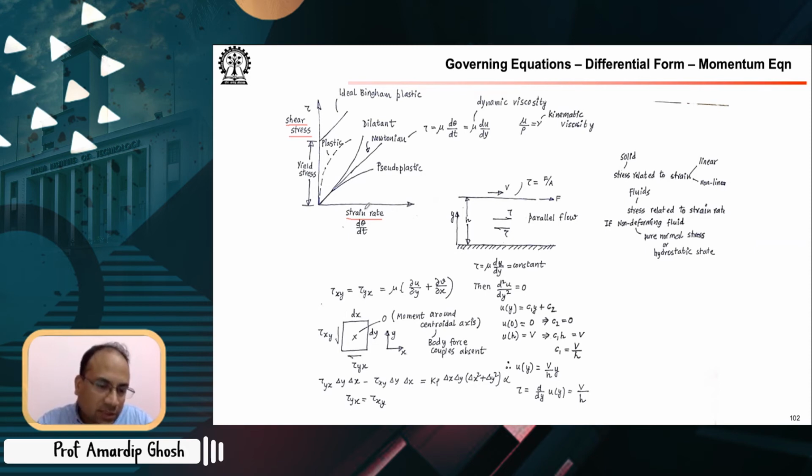So essentially, you apply a stress. Stress is nothing but force per unit area. If you apply a stress, it creates a strain, the solid deforms and it resists the stress that is causing it, and then we can calculate what stress is causing what deformation, and from deformation divided by initial dimensions, you can find the strain. So that is the stress strain relationship in solids. In the case of a fluid, it can be a gas or liquid, the moment you apply shear stress, the fluid will start to show strain. Strain is deformation.